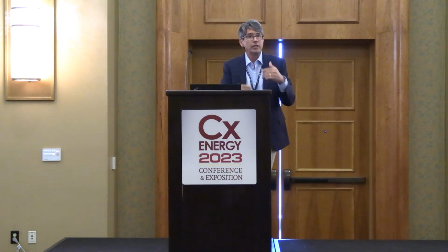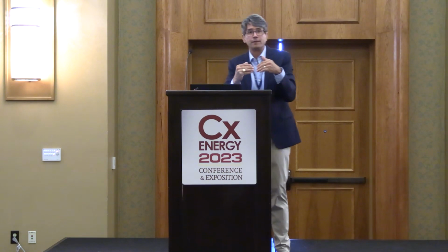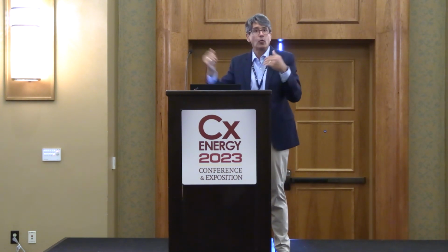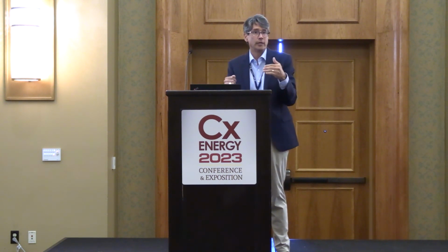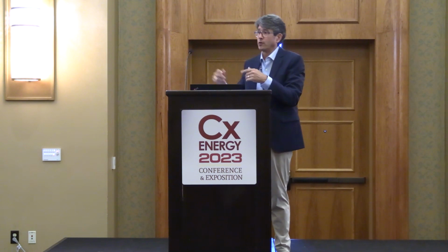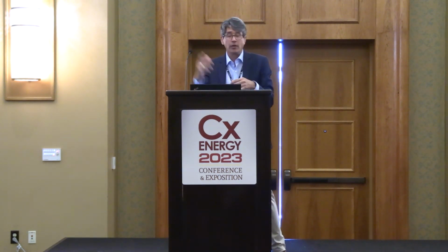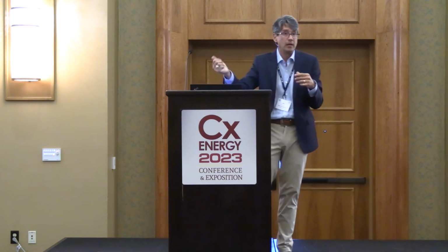So if you're going to need some numbers like that and some proof, or better yet, they want to calibrate and make sure their sensors are right, we need to make sure with that supplier that we have availability to test ports, or they're going to run two off to the doors to match up. And that's all they really had to do: tee off the tubing they had, put a set of test ports on the exterior of the panel, and they said that wouldn't have been that bad to do. If we know that ahead of time, we can get those kinds of things taken care of in that scenario.